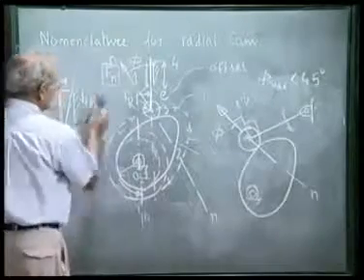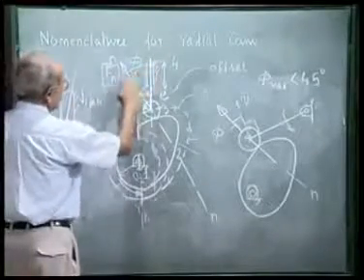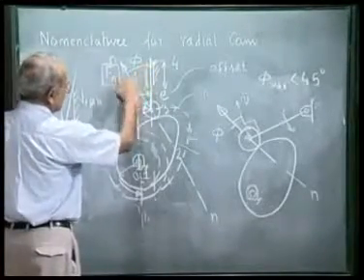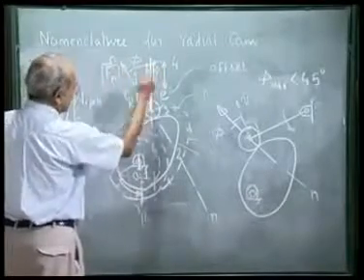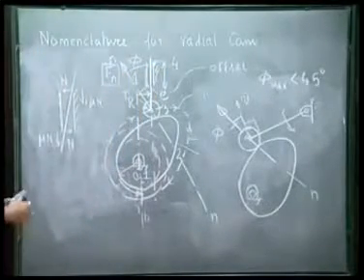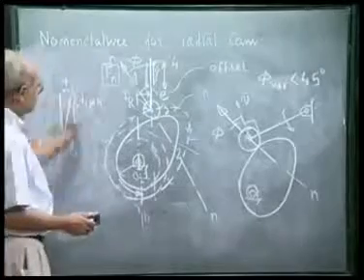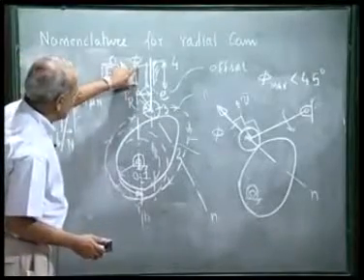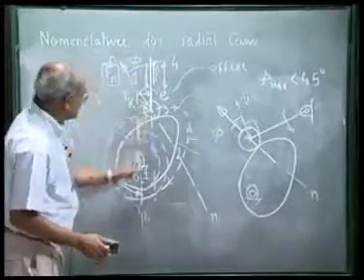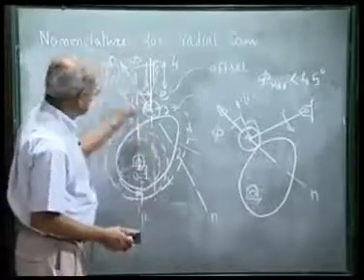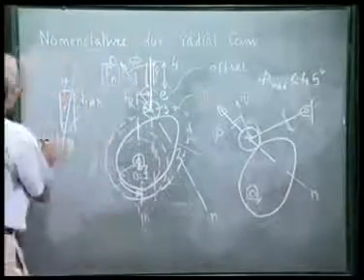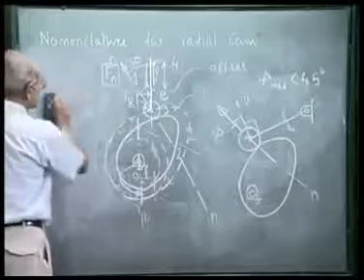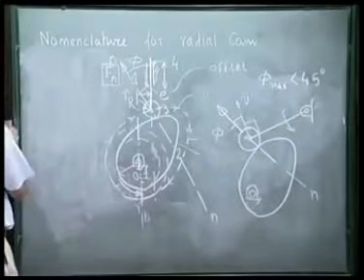So it is obvious that this vertical component will be Fn cos phi. If the phi is very large, then this vertical component will be reduced. As a result, during the upward movement, I want phi to be low, and during the return movement, that is the downward movement, phi can be large. So phi max is more critical during the upward movement.